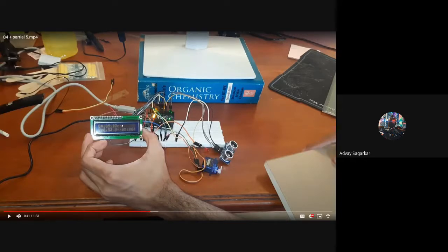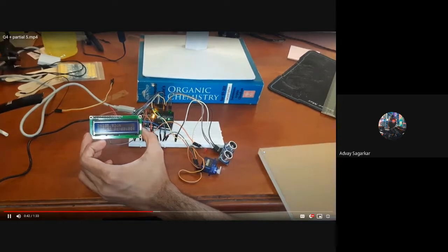The distance is right now showing quite a large value. I think that was due to the book that I was keeping. Since I was filming, it was not actually blocking the actual cone of the ultrasonic sensor, so it was not rebounding off the wall or something. Okay, no problem. We understand that part. Yeah, we are also getting it.